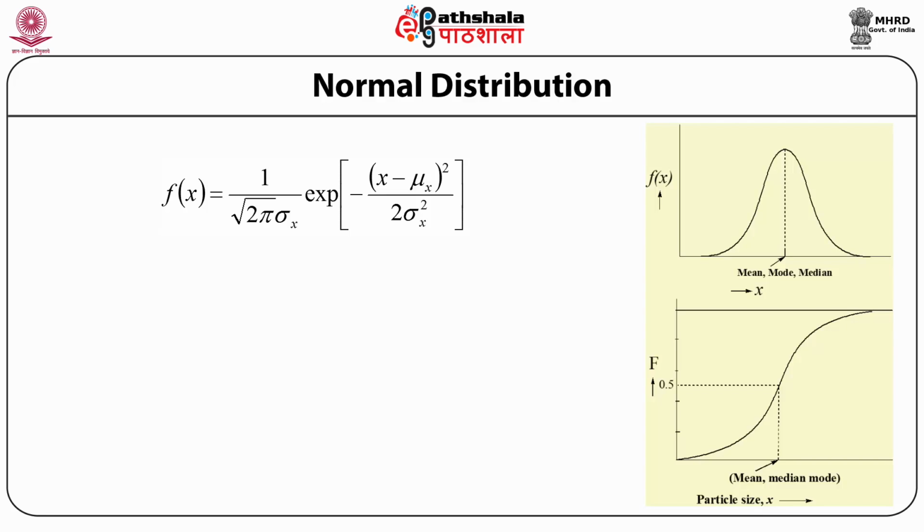This distribution is usually followed by powders produced by milling of fine-grained minerals and calcine aggregates. Other functions to which the particle size data can in some cases be fitted are the Rosin-Rammler equation and the Gaudin-Schuhmann equation. First we will discuss the log normal distribution.